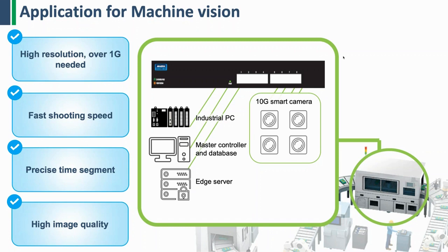The third approach, which is becoming more and more prevalent in the industry, is to take the raw streams from the camera to a central vision processing system, loaded up with lots of memory, CPU, graphics cards, etc. The cost per camera actually comes down, and you also have expandability. The challenge with the third approach is that we're taking video streams from the cameras in raw format.